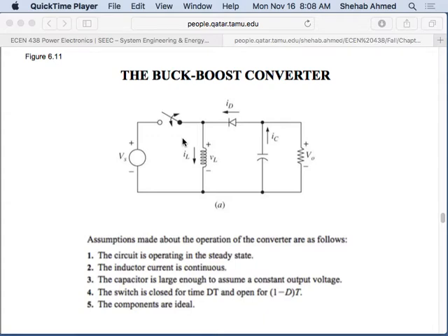And there's always, at the terminals of the two switches, or I call a diode the switch, right? It's an uncontrolled switch. So at the terminals of the two switches is typically what we call a stiff voltage source. In the buck boost converter, there's a stiff voltage source here, which is a capacitor. It's a stiff voltage; it does not allow voltage to change quickly. On the other side is a voltage source, or you can put a capacitor as well. And between the two switches is an inductor.